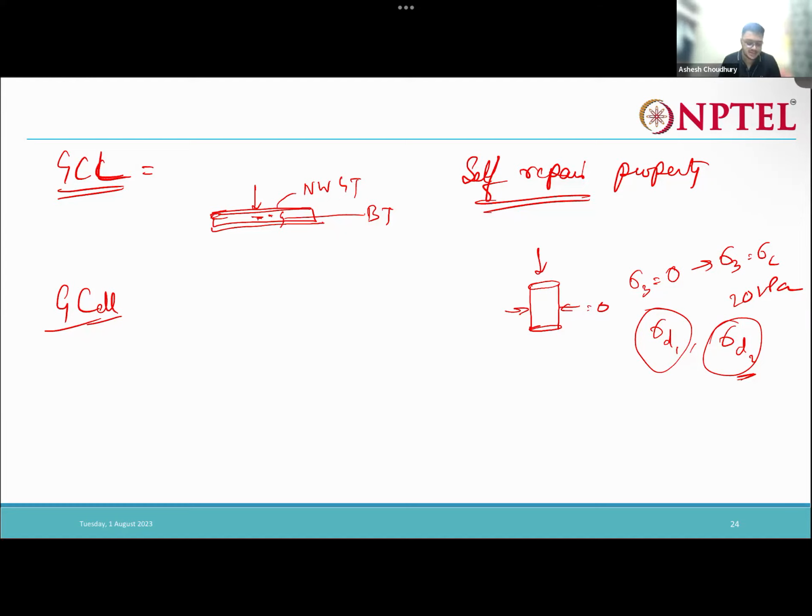So where are these geocells used? They are used as erosion control devices. They are used to protect steep slopes. They are used to build retaining walls, reinforced earth walls. Also as sub-base support, such as road bases, and railway tracks. All of these uses apply.